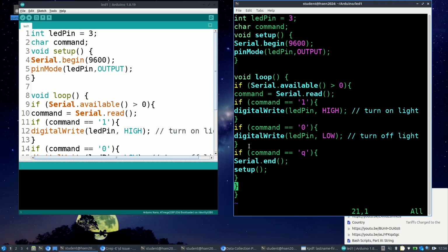Now we have to set up your circuit. I keep talking about LEDs, so this is what you have to do to your circuit. You've got to identify pin D3. Remember D3? When you look at the connectors here, and here's your cable, your USB mini cable is up here. Then D3 is down here.